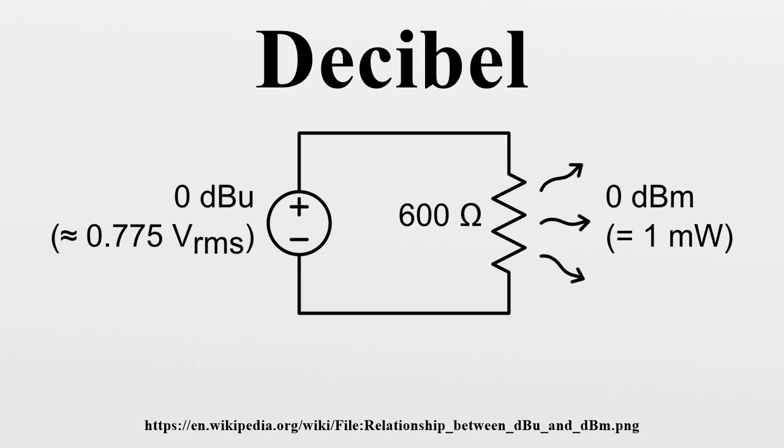Video and digital imaging. In connection with video and digital image sensors, decibels generally represent ratios of video voltages or digitized light levels, using 20 log of the ratio, even when the represented optical power is directly proportional to the voltage or level, not to its square, as in a CCD imager where response voltage is linear in intensity. Thus, a camera signal-to-noise ratio or dynamic range of 40 decibels represents a power ratio of 100 to 1 between signal power and noise power, not 10,000 to 1.